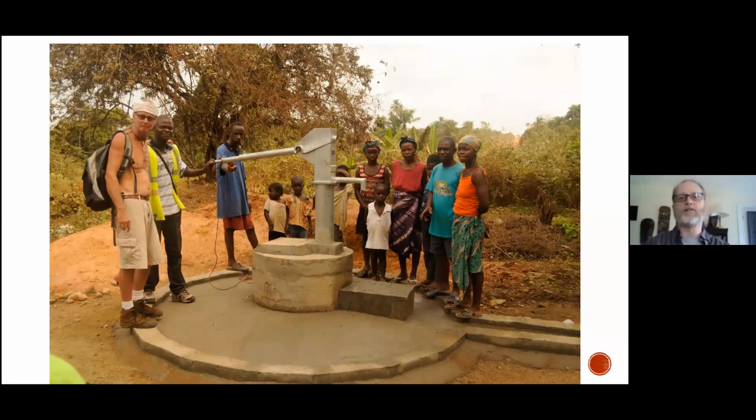So it's still a well, and it's still very functional, and the advantages, of course, are that there's no power requirements. Disadvantage, doesn't bring up a lot of water at each cycle, at each rotation of the handle, but it's reliable. And the most important thing for the communities where it's been installed is that it protects against contamination for the most part. Obviously, after water has been pulled from the well and into the containers, there's a potential for contamination there, but the well supply itself is protected. And that's really what we want. It's the same with the casing on the video that the well driller was talking about, ensuring that no surface contaminants can enter the well.